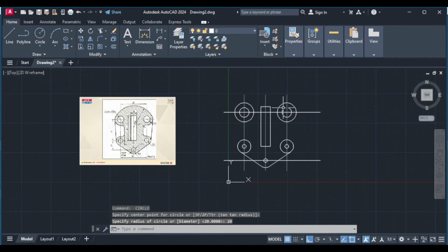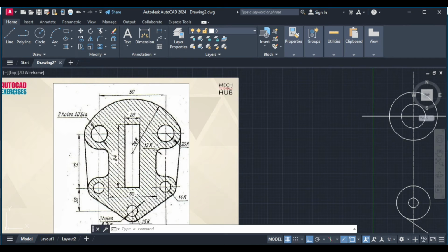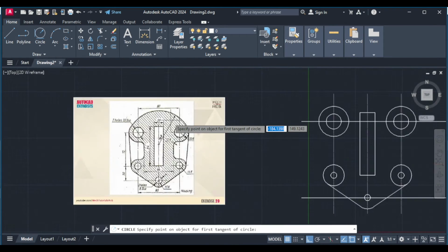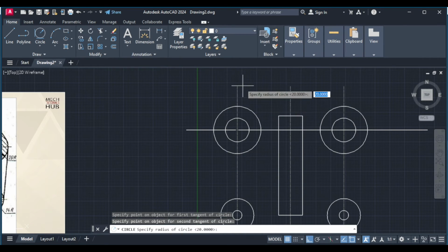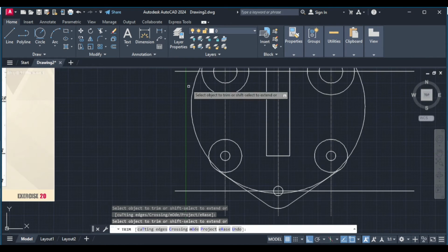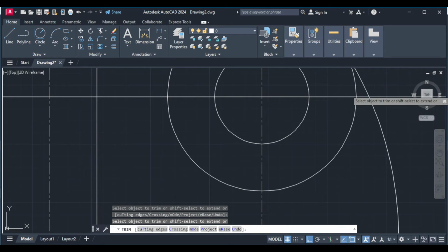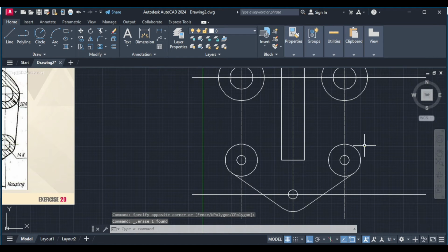So this is how it looks. Simply you have to draw a tan radius. Here this radius 74 is given. So I'll go with an option called tangent and radius. There, this is 74, from this point to this point. Then TR, double enter. What is unwanted here? This is unwanted. This is also. Escape, select the remaining part, delete. This is how it is going to be.